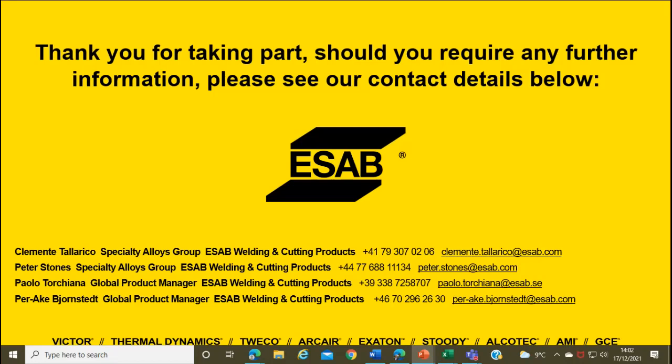Yes. Okay, good. Then we have a next one: would you need a longer run-in, run-out plate for starting and ending the electroslag welding process, versus submerged welding? Paolo, go on. Yes, sorry, I was muted. No, usually you don't need it, because you can start cladding and stop the activity on the same object that needs to be clad. Maybe you might need some light grinding, but there is no need for run-in and run-out plates. Right. Yeah, and I would say also that the electroslag process and the submerged welding, in principle, where you start is quite the same for what we have seen and processed.